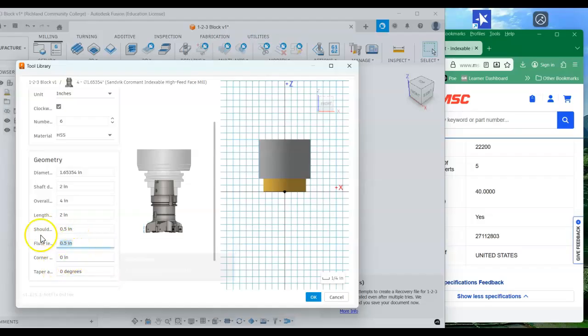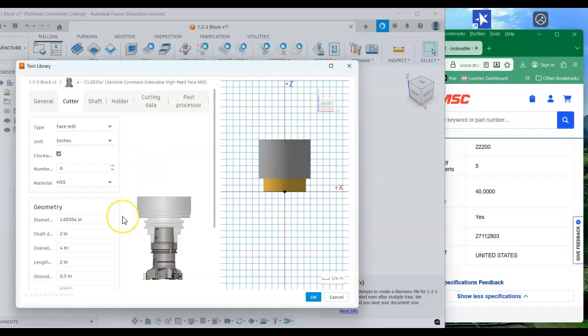On the short side of this, just to make sure that we can generate good code. To be honest with you, the only thing I really need to make sure of in terms of posting out for just a 3-axis mill is the outside diameter set. So if I'm using live tooling, where there might be interference issues with that cutting tool, I'm probably going to make sure that I have a lot more of those sizes set here for the machine and for the simulation, so I can double check and make sure it's not going to crash anywhere.